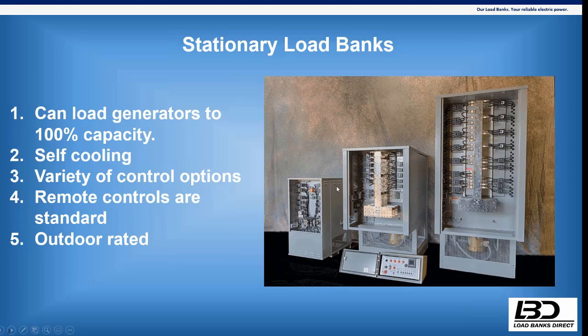So from 0 to 200 kW here, 200 to 800, and something similar to this, a single stack of resistors with one blower. And then the third one, that's up to 1250 kW in a single stack, one blower, one single stack of resistors. And as you can see, they grow pretty fast as they go up there.